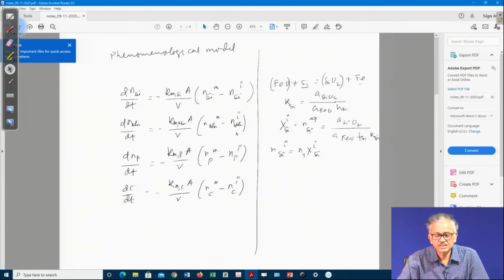Now, the interface concentration, as I said, at the interface you can assume equilibrium, that is, all the chemical reactions are at equilibrium at high temperature, since the process is taking place at 1600 degrees centigrade. So, the activation energy will be quite low and the chemical reaction will be fast enough. Only mass transfer can be rate controlling. That is the justification of this assumption.